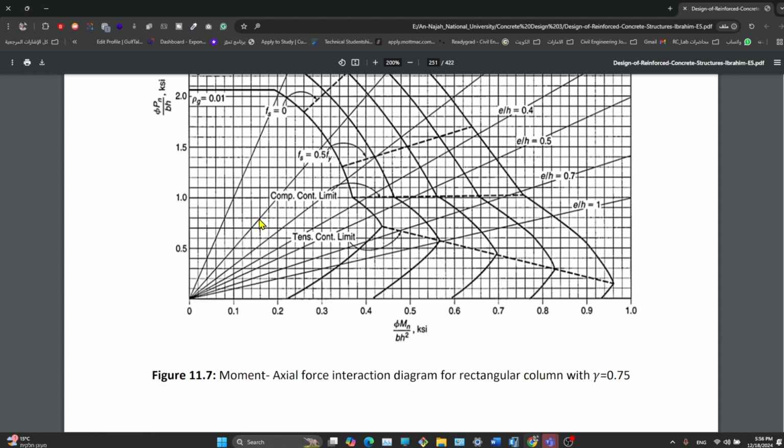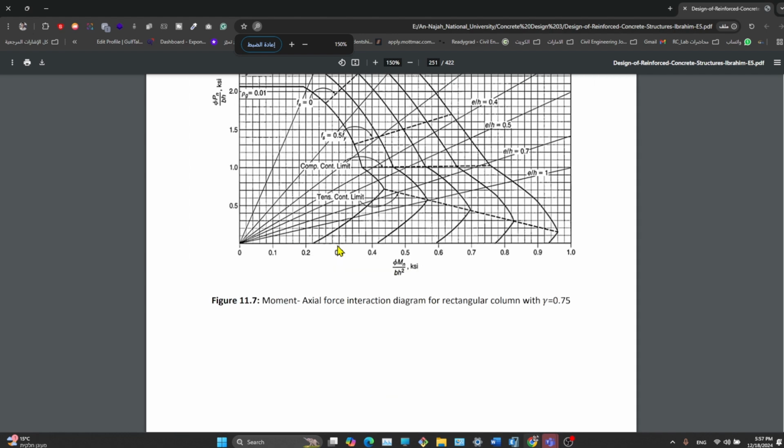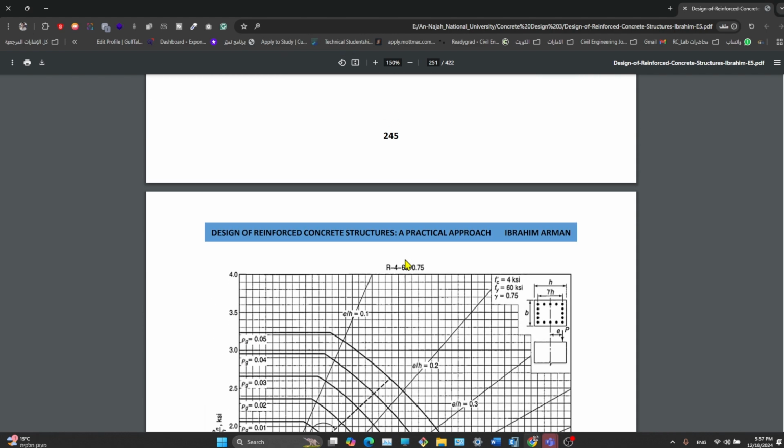So in this case, the column can resist the moment and it's safe for designing, considering a 0.4 by 0.4 column of height 6 meters under that P ultimate, which is equal to 1036, and M ultimate, the magnified moment, equal to 105 kilonewton. I hope everything is clear, Muhammad. Yes. Do you have any questions? No, it's very clear.